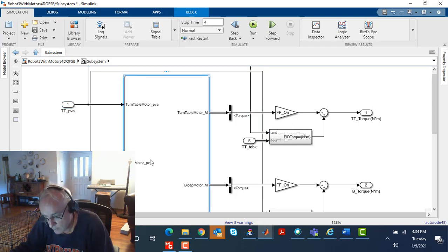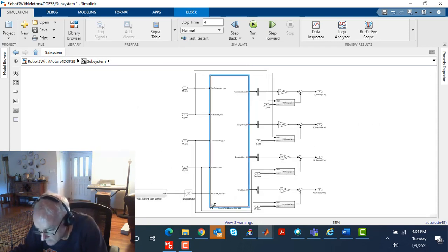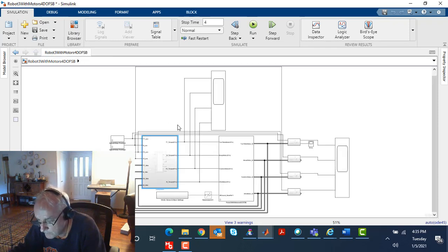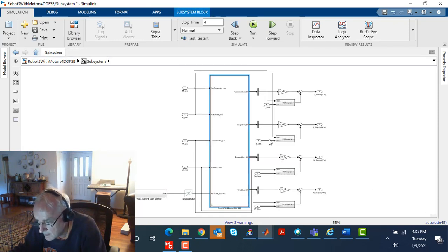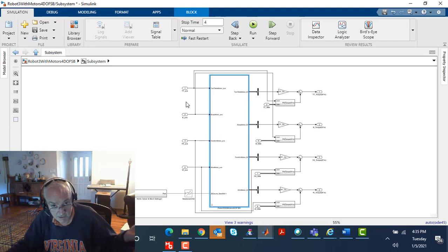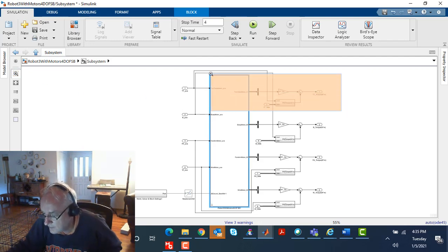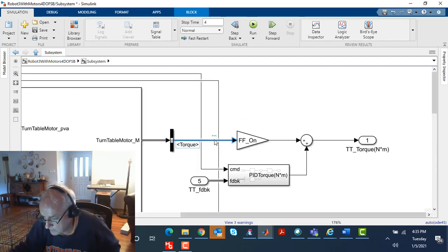This algorithm, which is based on the Simscape Multibody blocks, is in what they call the inverted mode. Therefore, it takes a motion request and tells you what forces or torques are required to do this. That's our calculation of our feed-forward torque coming out of that model.